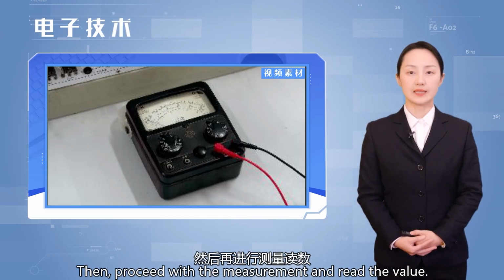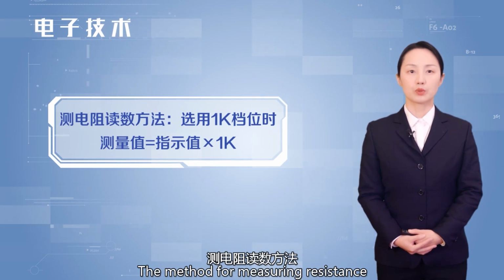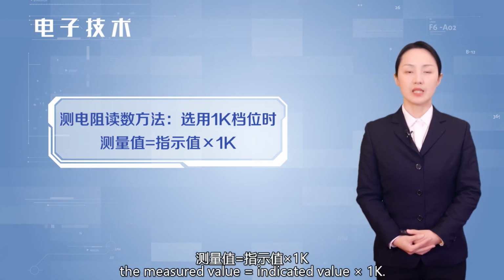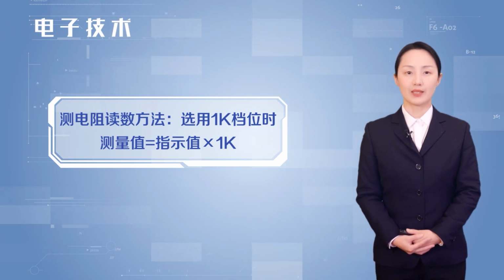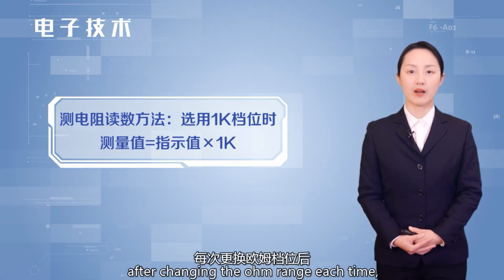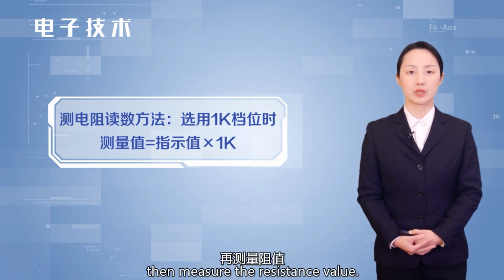Then, proceed with the measurement and read the value. The method for measuring resistance when using a 1K range is: the measured value equals the indicated value times 1K, and so on. It is important to note that after changing the ohm range each time, remember to perform an ohm zero calibration first. Then measure the resistance value.